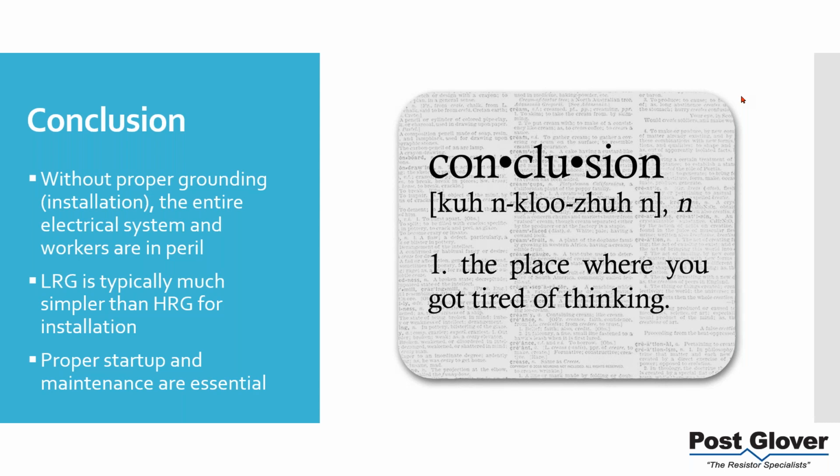Well, I do know the working clearance is, I honestly don't remember where it's at, but it's probably in the NEC. But it definitely is a requirement that you need. So you're going to need that 4 foot. In terms of the other foot, it's going to be typical. You have to remember that most manufacturers now, it depends, right? A lot of manufacturers do it the same way in terms of low resistance ground.